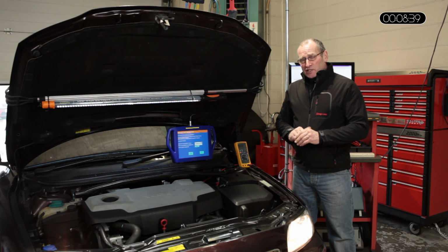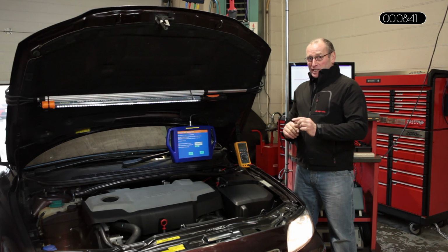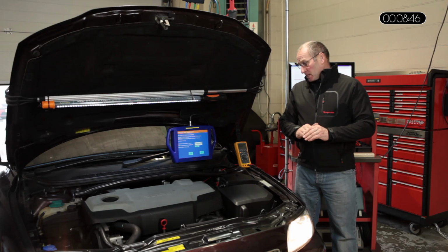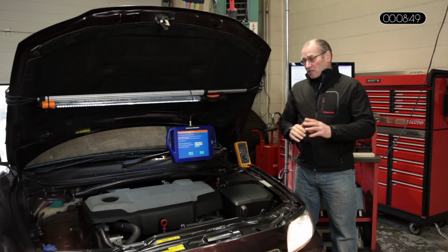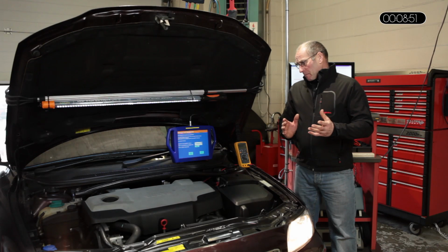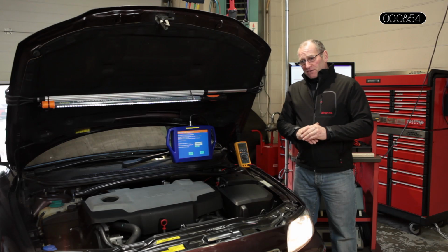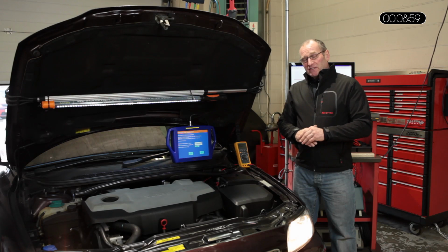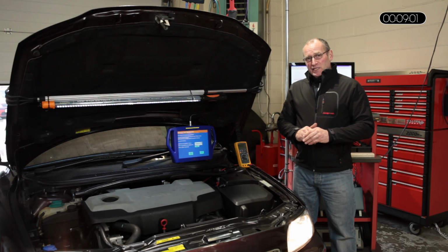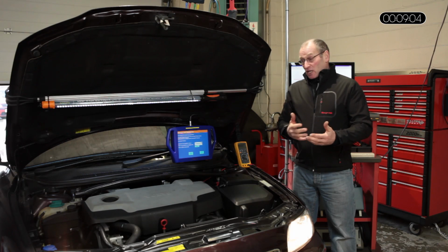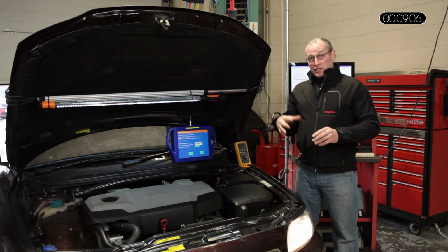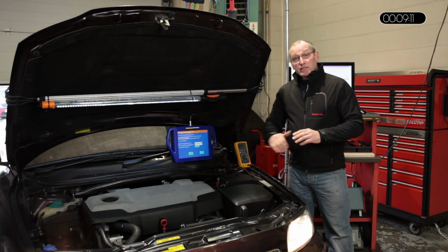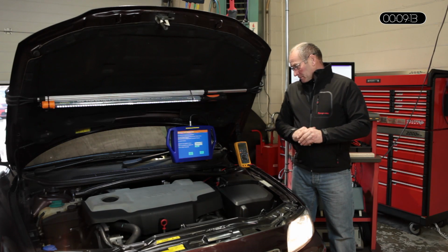Originally, when I test drove this vehicle, this is on the road, not static, we had a maximum reading of 22 grams of soot. Now, we're still collating data. Part of our function, apart from repairing vehicles, is collating data, so we're able to intuitively know at what point systems start to go into default. So we're still collecting these figures, but we are quite confident on some of these figures and on some of these voltage readings. So we had 22 grams of soot on full load.